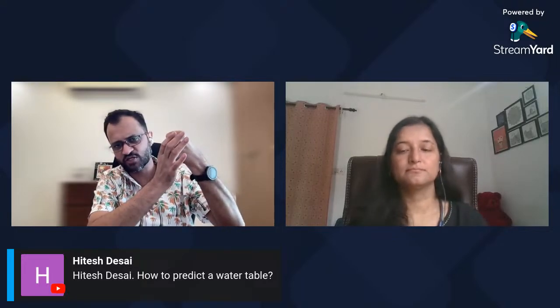Good question, Mr. Desai. Since in a piezo cone we are measuring the dynamic pore pressures, what you get is this: when you are pushing the cone in clay, because of its low permeability, your dynamic pore pressures will spike up, because of the effect of the cone.